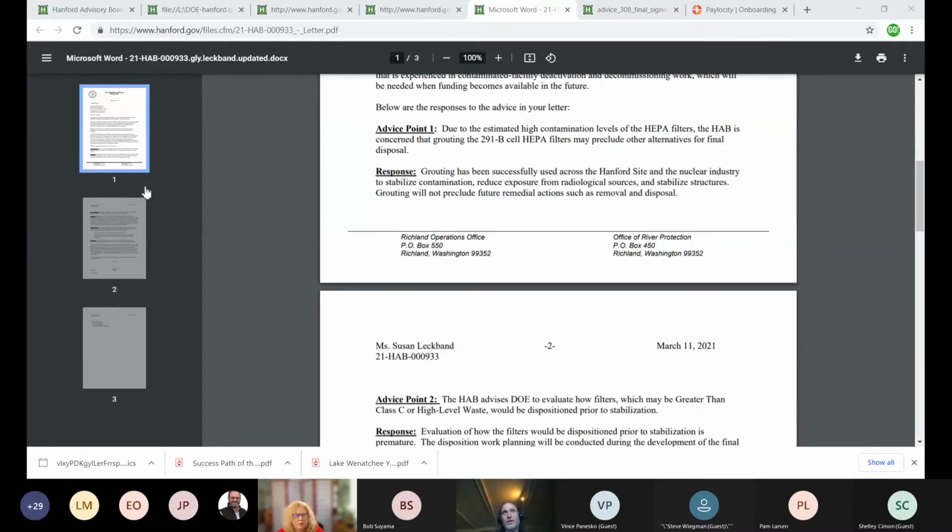which, you know, I would feel more comfortable filling this with sand or gravel to prevent a collapse. That's easy to vac out, and it won't be as quote unquote permanent as the grout. So I feel like that's something that was missed in this response, where it was automatically knee-jerk grout is good, where it could have been something to fill the space to prevent a collapse is good. So a little subtlety. I was wondering, do we have anyone from EPA on that